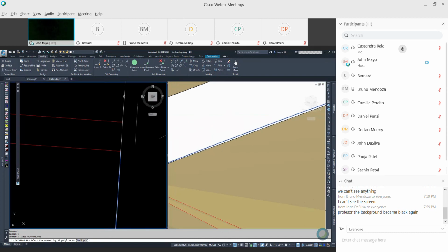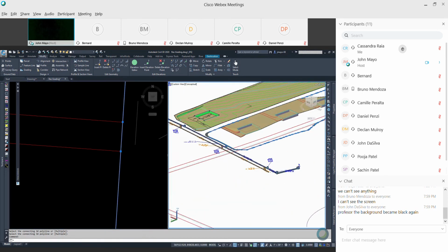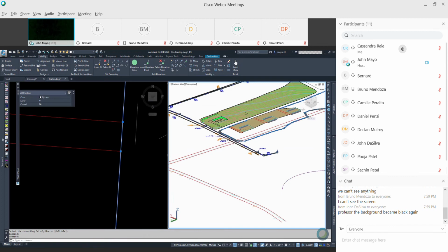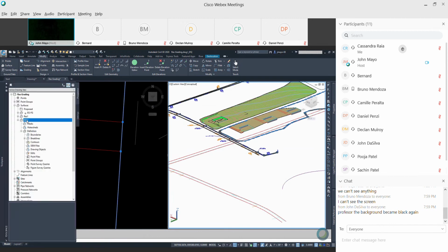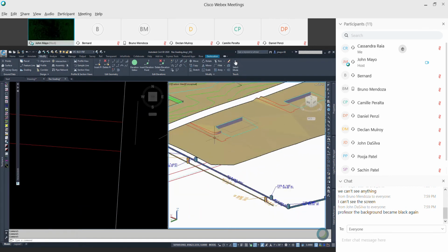But regardless, your feature line join command will join them back up. And you can just put that back into the surface. And as I said, it's not going to be defined as I'd have to redefine the boundary. And again, I'm just going to wait for that because I don't want to mess with that a lot. Look in the 3D view, we're back to where we were.